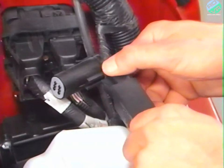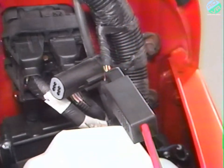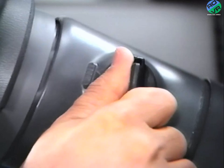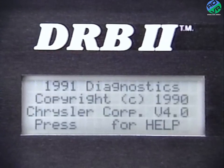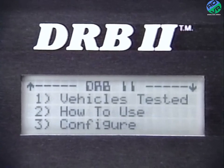The DRBII connects to the fuel injection system through the diagnostic connector located here on Wrangler models and here on Comanche and Cherokee models. To power up the system, turn the vehicle's ignition key to the on position. The first thing you'll see on the DRBII screen is the program version number and Chrysler Motors copyright message. This screen will appear next. Press the down arrow to view the rest of the screen.